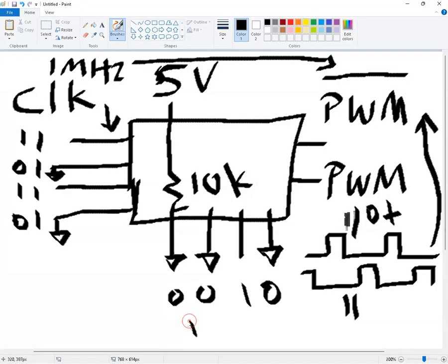So we can determine the dead time control by doing this, and we can determine the clock. If we put probably 100 megahertz, and we do this, it could divide down to any combination of switching frequency we want, and we could have different nanoseconds or microseconds of dead time control.